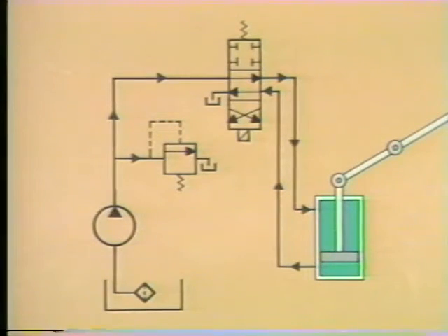To get the piston to move back up, the flow paths have to be reversed. Now we want the pressurized fluid to enter the bottom of the actuator and to push up on the piston. And we want the fluid to leave from the top of the actuator. This can be accomplished by sending a control signal to the directional control valve. The control signal causes the internal mechanism to move, shifting the flow paths inside the valve. Incoming and outgoing flow, in a sense, change places.